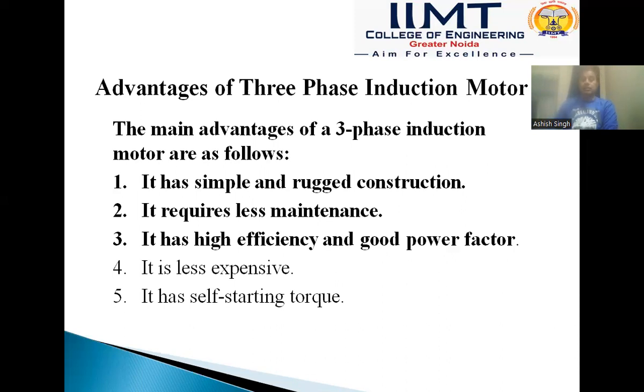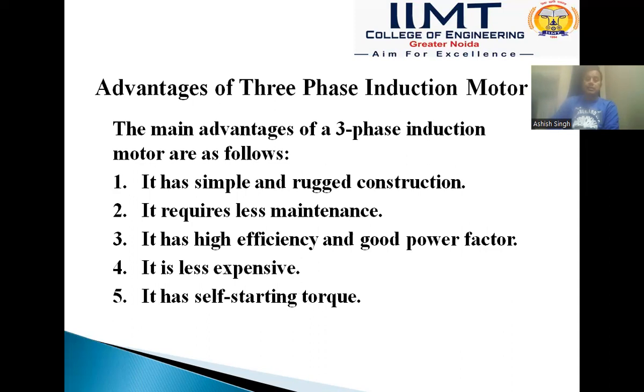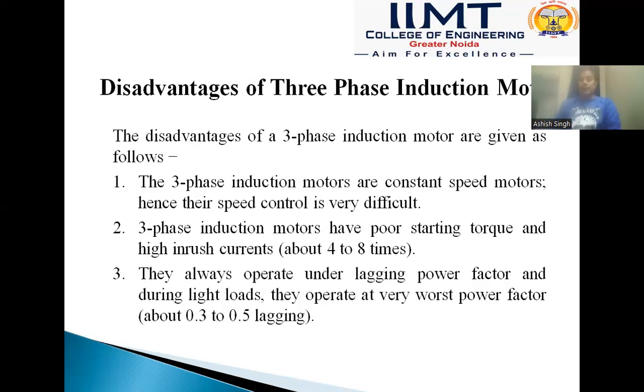Third, it has high efficiency and good power factor. Next, it is less expensive as compared to synchronous motors or DC motors, and it has self-starting torque. That means we do not require any additional starting winding.